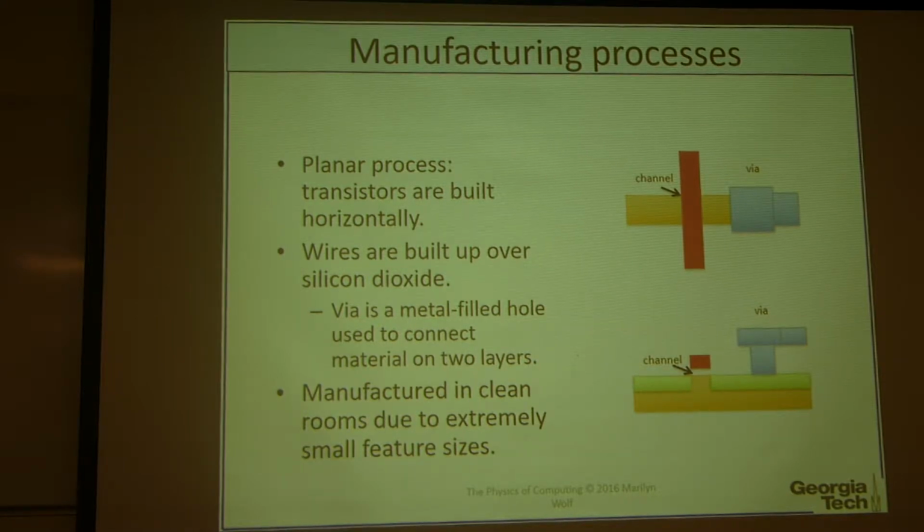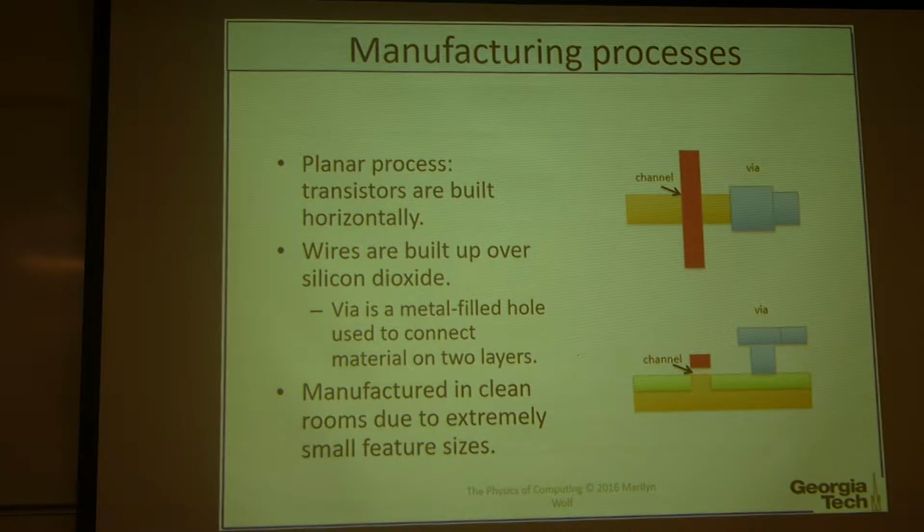And then they should be manufactured in very clean rooms, clean areas, because we are dealing with micrometer or sometimes sub-nanometer regime. For our Marcos clean room, we have a class 100, which means we have approximately 3,520 particles within a cubic meter. For typical urban areas like here, it would be like 35 million particles per cubic meter. For industry, it should be a lot cleaner.